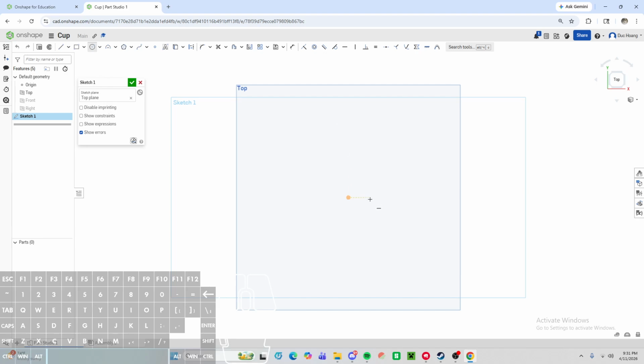And what this orange line does is, you'll notice that the center of that cross is not perfectly in line with that line. If that makes any sense. It can be a little bit above or a little bit below, and the line will still appear. And because the line is there, that means that if I were to place the first point of the circle right now, it would be perfectly in line with the origin.